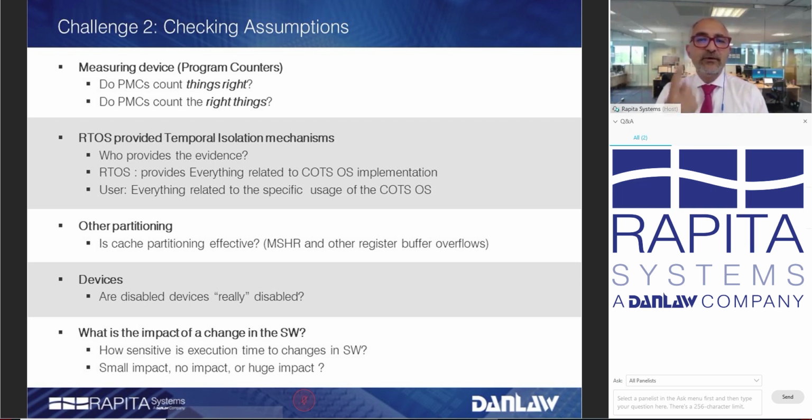This is a single point of failure. All the accesses to the cache can be partitioned, but not the exit of the cache going all the way to the memory. If one core, one part of the cache, collapses that bus or that buffer, the other part of the cache, when it needs to go back to the memory, needs to queue as well. And if that buffer is full, then that blocks the whole system.